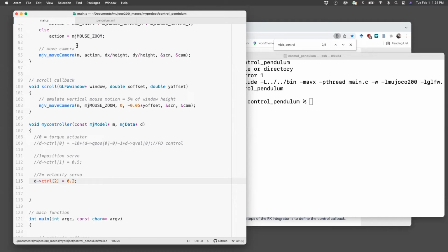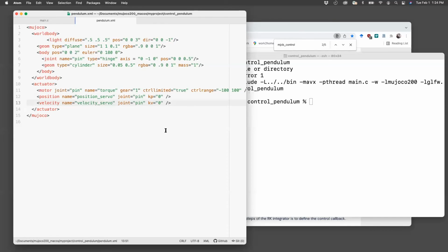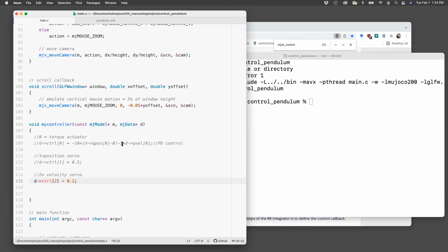Okay? And remember that we set the gain to be 0, so we need to change that. Now if we use too small a value, then it has to basically fight gravity. So we make it big enough that it doesn't have to fight gravity. If this works all right and the gain is big enough, then it'll move continuously at a speed of approximately 0.2 meters per second.